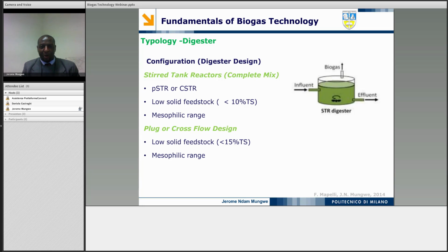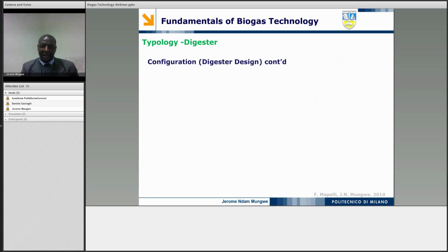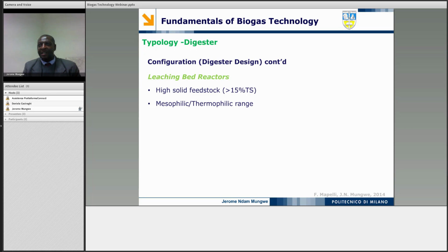as compared to the completely stirred tanks, and they also operate at mesophilic range of temperatures. Then we can also look at the digesters as leaching bed reactors or leaching bed digesters. This type of digesters can operate at very high solid content of the feedstock, greater than 15%, and they can either be mesophilic or thermophilic.